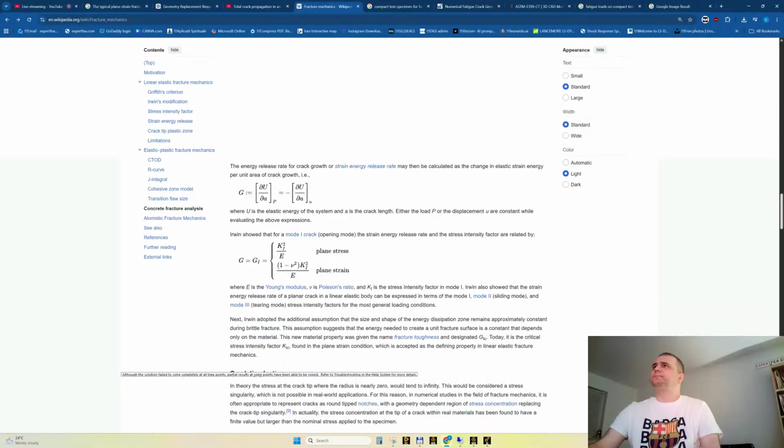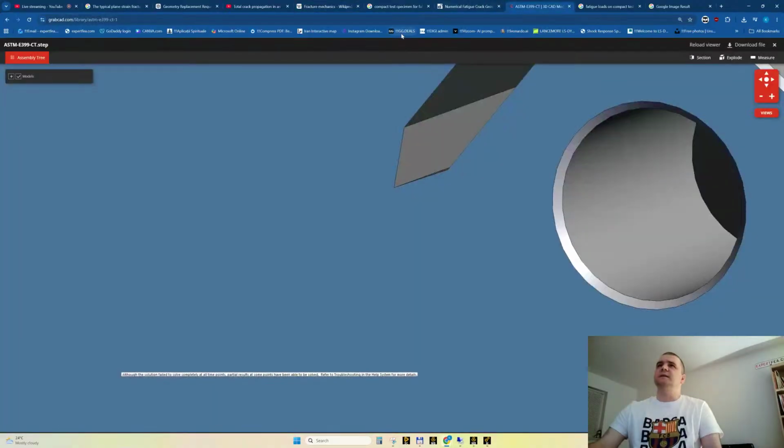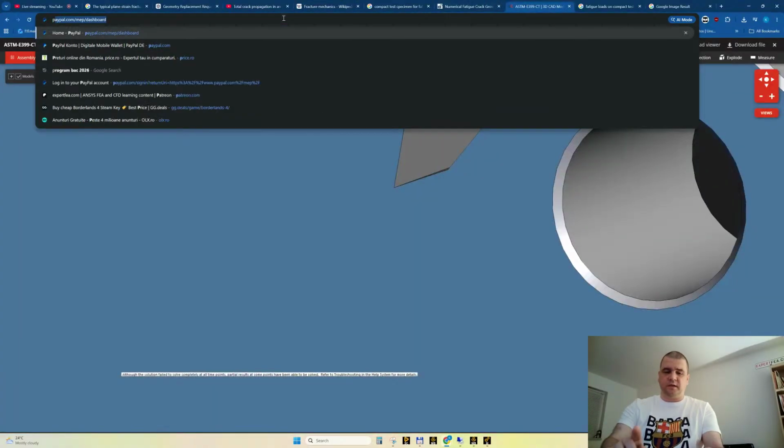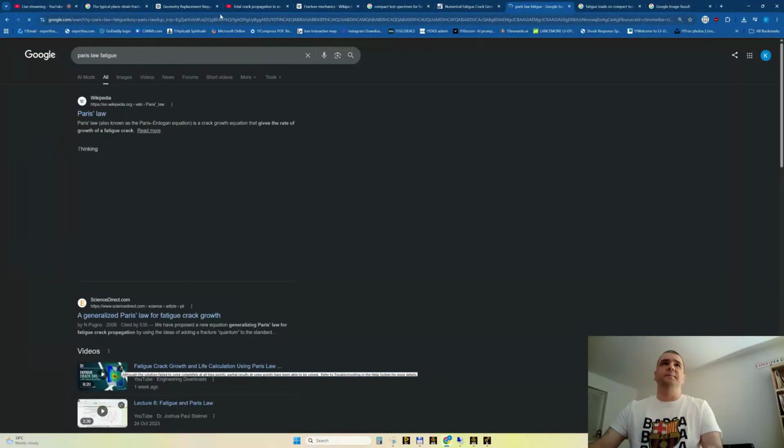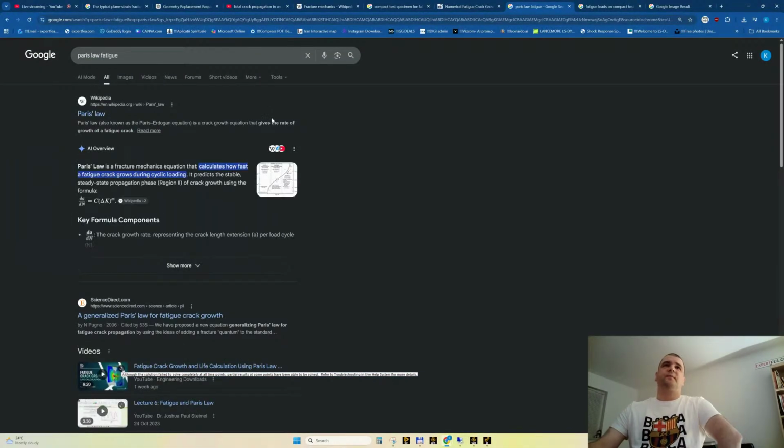Let me see if I can show it. Paris law of fatigue, something like this. It is a crack growth equation that gives the rate of growth of a crack. In principle, this is the equation, as I showed you a few minutes ago.